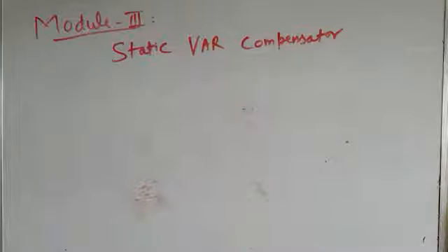It's basically a shunt compensator which exchanges reactive power with the system bus or with the transmission line, and hence it results in various advantages, like it increases the power transfer capability of an existing transmission network. It helps in quick damping of electromechanical oscillations or power oscillations. Okay, it provides voltage support for voltage balance of a system, and so on. So these advantages we have already discussed.